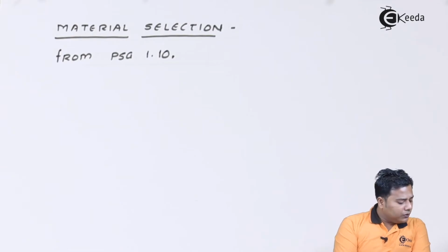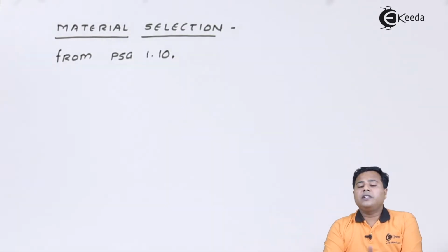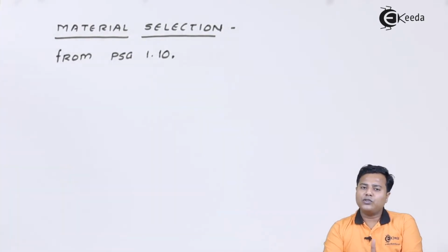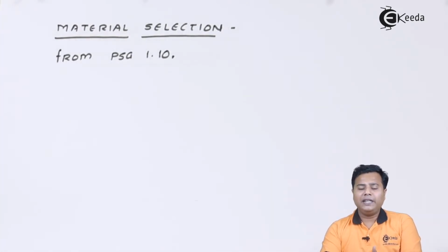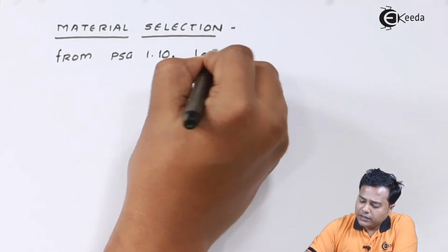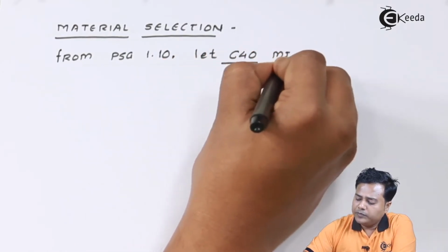machine parts. Let us go for C40 as the material because that is generally used for the spindles. Spindles are kind of things which are related with power screw. So we'll go for C40 or C60. It's up to you. Accordingly, material properties will change. Of course, cost is not a concern for us right now, so you can select that material, but it should be in line with the application. So let C40 be the material.